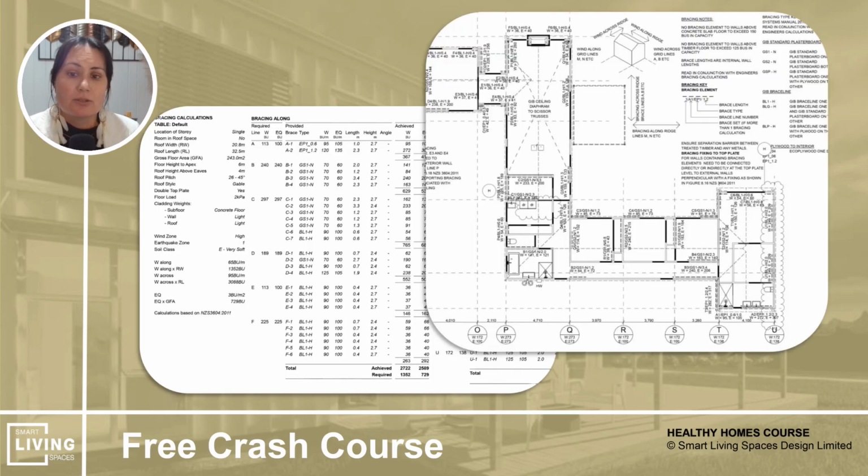Also, wall linings are used as bracing elements in our homes. So if you just remove them and don't do bracing calculations, your home structure will likely be compromised in the case of a storm or earthquake situation. So buildings in New Zealand legally have to be braced for wind and earthquake, and how they brace does depend on your home's design. So if your walls have been insulated without a consent and bracing considerations, in the event of a natural disaster, your insurer might not pay out because you have illegal building work.